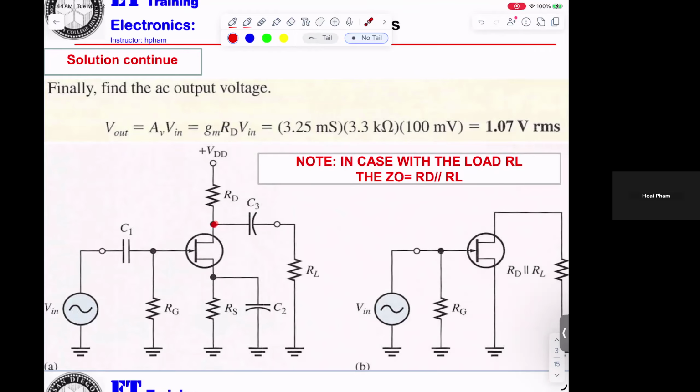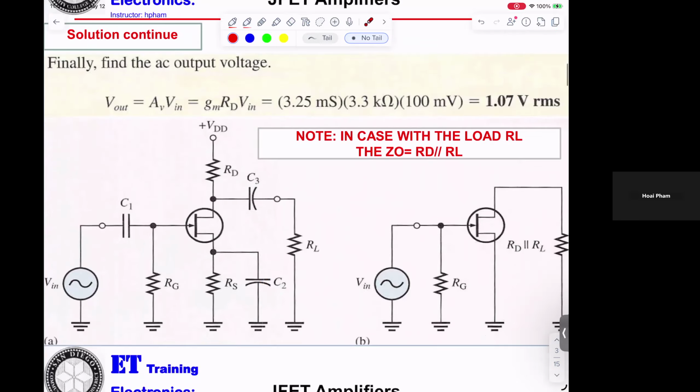That means you get a true voltage. So when they go into the load here, it's a speaker. Speaker cannot allow DC coming out. So that's why you must get C2. Okay? And the same thing, C3 here. It's a bypass. Okay? Same thing as in the bipolar. Okay?